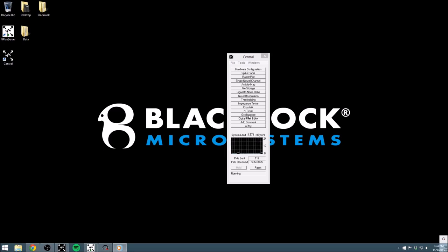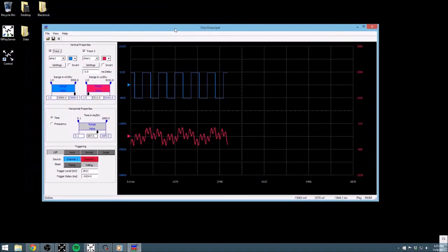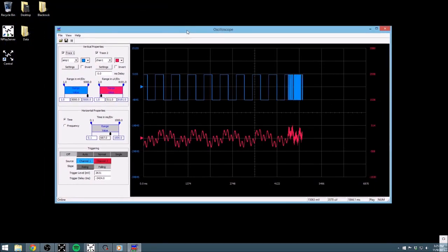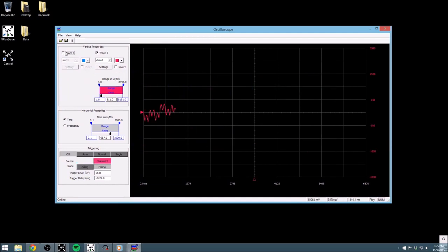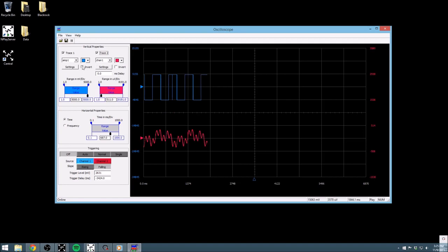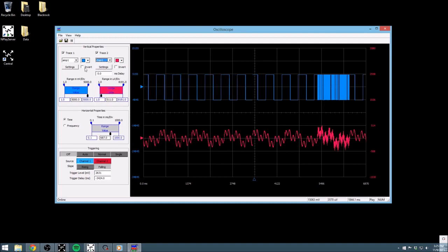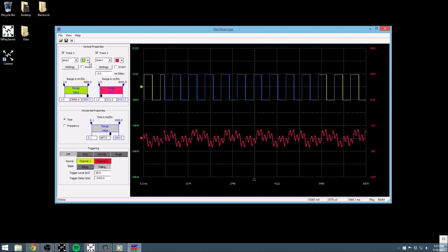It enables you to look at the signals more closely and with greater time resolution than many of the other central modules. This oscilloscope is a two-channel oscilloscope. Each channel can be enabled separately by using these checkboxes at the top of the window. After enabling a given trace, we can use the drop-down to choose the channel represented from any of our available analog inputs, which include our amplifier channels and B and C inputs on the front of our processor. The color of the trace for that channel can be selected in the exact same way.